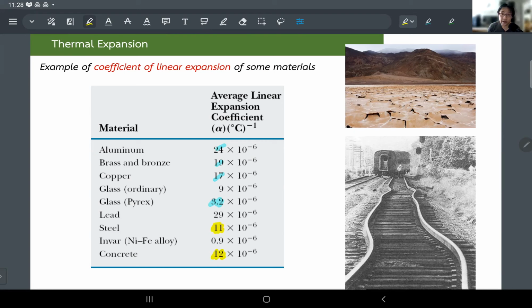And now you see the reason why. Every time you build a skyscraper, buildings, constructions, everything, you have steel reinforced concrete, right? And of course, that means in that structure, you have concrete and steel together. So during the daytime, they get the same amount of heat from the sun and all that stuff. So they're supposed to expand and contract at the same rate. Otherwise, you're going to destroy some concrete. Maybe some steel just pops up and cracks the concrete and all this stuff. So that's why, for engineering purposes, you want the steel and concrete to have the same coefficient of expansion. It has to be. Otherwise, they're going to have some problem right there.